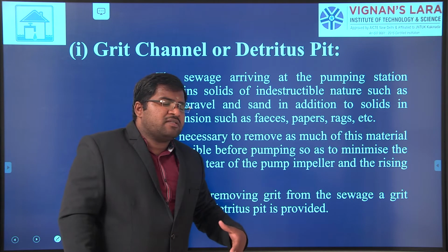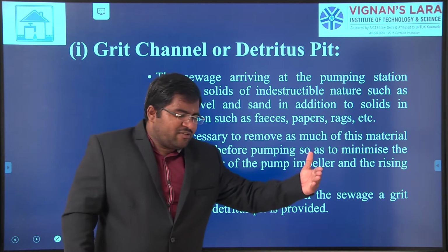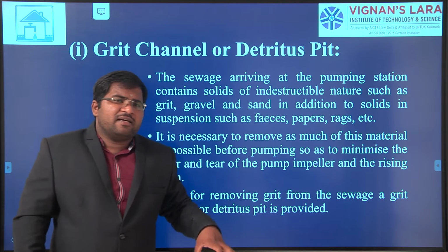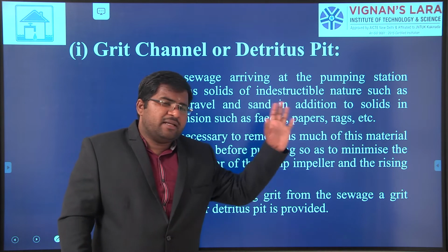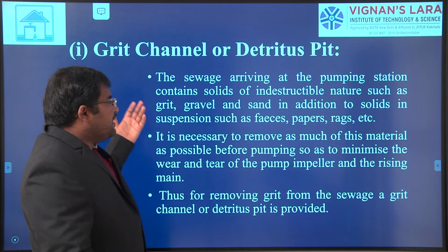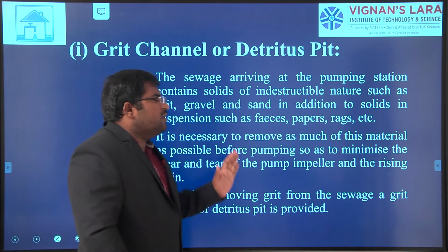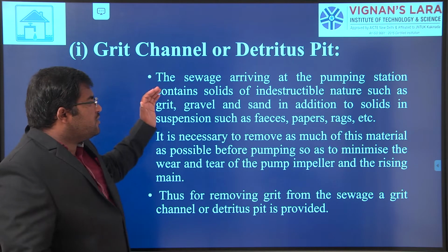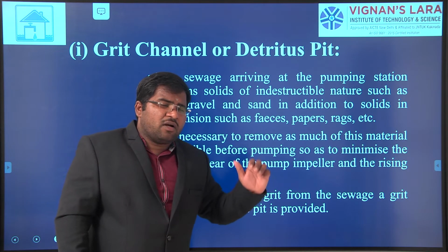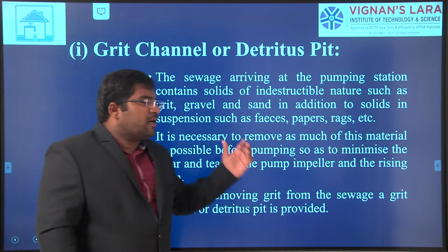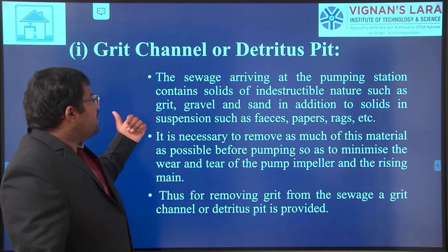In the case of sewers also, we said that there is a self-cleaning velocity. When you reduce the velocity, settling will occur. If you increase the velocity of flow, it will carry all the materials. Now in the case of sewers, that high velocity is required. But in this grit chamber, we need to reduce the velocity of the water flow so that the grit particles carried along with the sewage will settle.